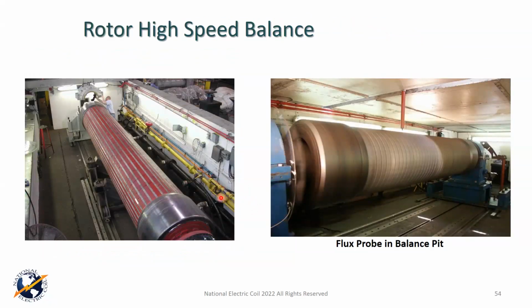So the last thing I want to tell you about the rotor is high-speed balance, and this really isn't about a component. I put it in because there's a misnomer about high-speed balance. Everybody thinks, because of the name, that the purpose of this is the high-speed balance. And I'm here to tell you that I don't see it that way, okay? The real purpose of high-speed balance is to requalify this rotor mechanically and to requalify this rotor electrically. Oh, and by the way, because we have it in this fancy facility, we'll balance it too, okay? But the important thing is to requalify it mechanically, requalify it electrically.